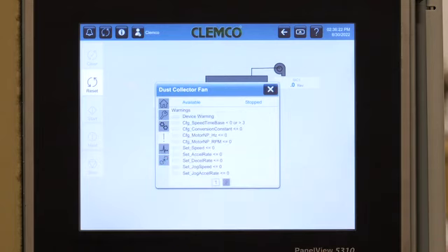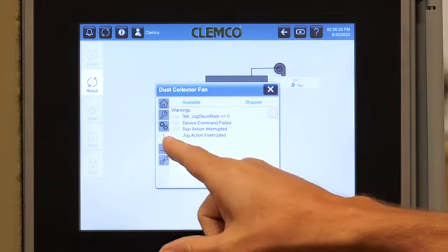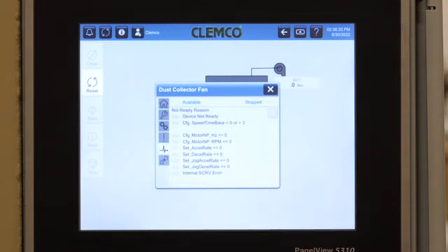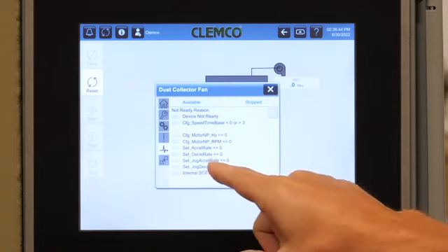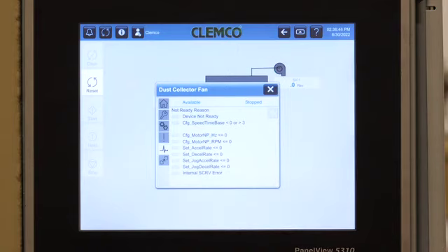Warnings. So any time the smart device gives a warning up to the HMI, you'll be able to see those statuses here. There's 2 pages of them. There's a help one that talks about, again, other statuses or setups that you have wrong. Let's say I went in as the manufacturer and set a setting out of bounds that doesn't make any sense. This would warn you about that. For instance, the acceleration rate less than 0 doesn't make sense.